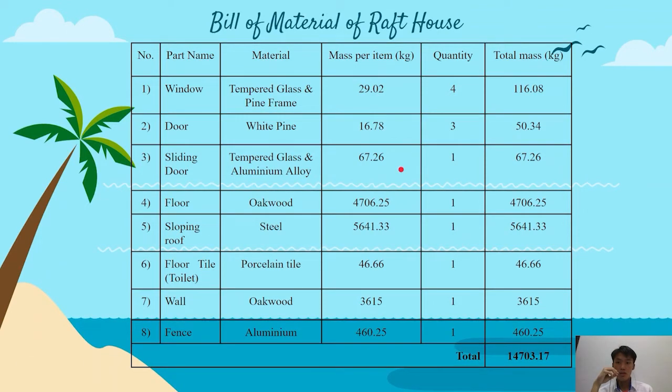The material selection for the window frame is fine because it is structurally strong but not overly rigid. And the material selection for glass is tempered glass because it is 4 times stronger than untreated glass. The way of calculating the mass of the window frame is by using the software application SolidWorks, and the mass of the glass is calculated by using the online website Glass Weight Calculator.